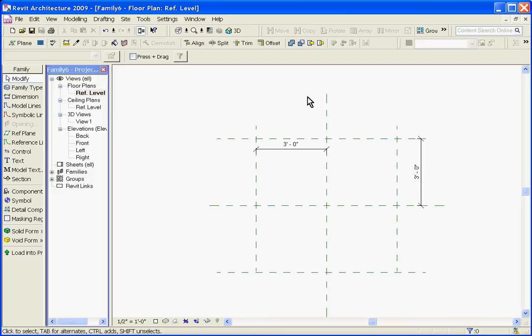In this case, for the width and depth, we have a center reference plane, and we want to make sure that that stays the center, even though the width and depth will change. So to do that, we want to lay out a dimension chain and equalize it so that the center always remains in the center reference plane of the model. So to make sense of this, I'm going to delete out this old construction dimension. I'll go to the dimension tool, choose the left edge, then choose the center, and then go over to choose the right edge. And then I'll drag it up and place it.